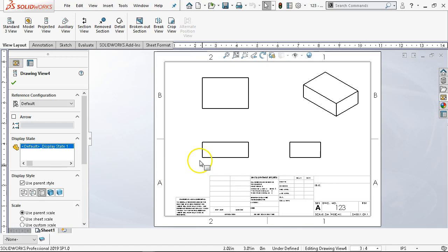All right, so once we get into the stack ups, I would go add sheets, add the next part, get all of my parts into position, start getting that overview of how these pieces assemble and go together, so that I can start thinking about what are the critical tolerances that I want to drive with GD&T.